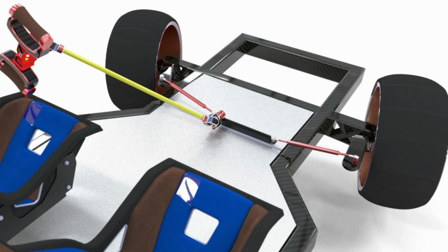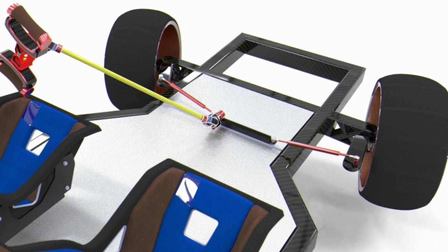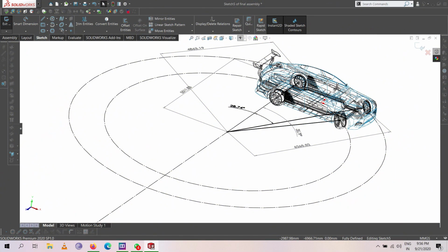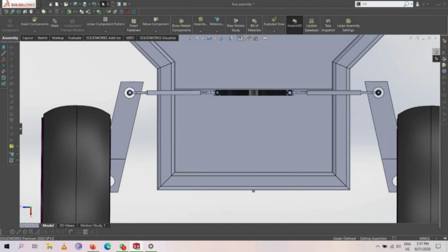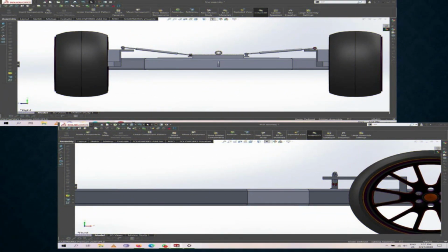The one thing we have to see when we look at this is each tire has a path of different radius. What that means is that all tires are rotating at a different rate. The one on the outside travels a further distance than the one on the inside in the same amount of time, so it's rotating more quickly. Now what does this mean? This means the right side is moving faster than the left side when we are going on a left-hand turn, and vice versa if we are going on a right-hand turn.